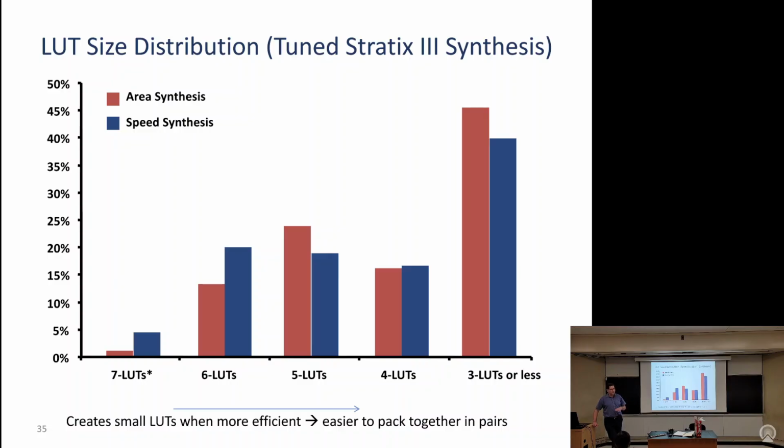So it does make all your wiring work, but we actually analyzed this on a bunch of end user designs, and I remember one analysis showed that like 15% of the design logic was muxing, right? So there's a lot of muxing in data paths. It might be even higher now. But that muxing has dynamic select signals, right? It's like a packet came in and based on its ID, you steer it to this unit or that unit, for example. And you can't do that with the routing muxes because they're statically configured. You can't suddenly say, now start changing this wiring to that wiring. Only the LUTs can do that.